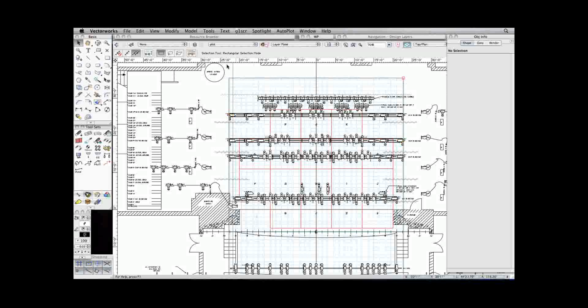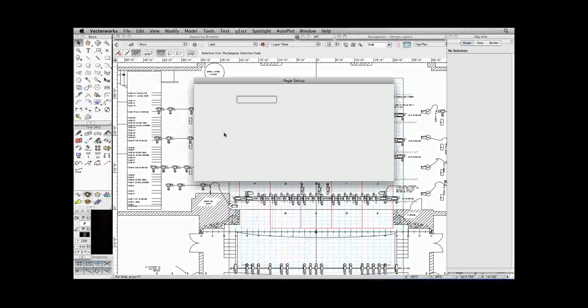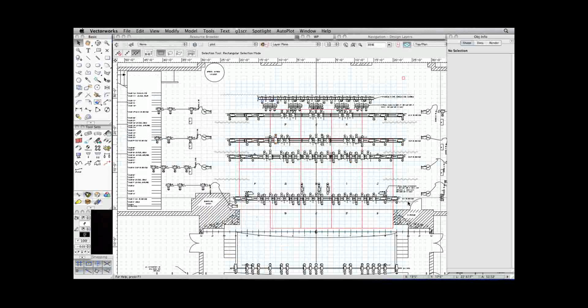And I want the grid over my whole drawing. Since I'm not worried about printing or page size when I'm working on the design layers, I usually turn off that option so that my grid is over the whole drawing as opposed to just on that page.